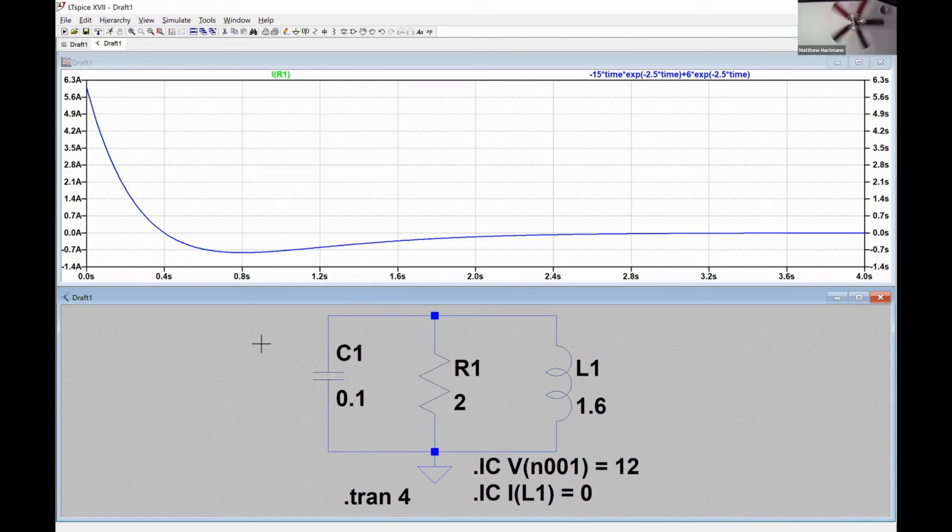All right, well, that's really all I had prepared for today. It's really just for the next couple of weeks, correctly identifying whether or not you have a parallel or series RLC circuit, determining whether the circuit is critically damped, overdamped, or underdamped, and then applying the table. So hopefully it's fairly straightforward. If me or whoever you had for circuits 1 did a good job of teaching you the transient analysis for first order circuits, this shouldn't be wildly difficult.